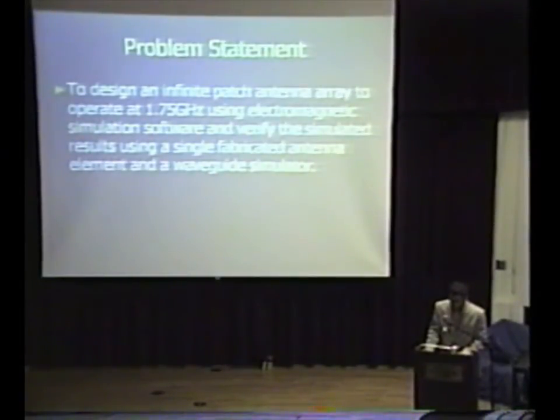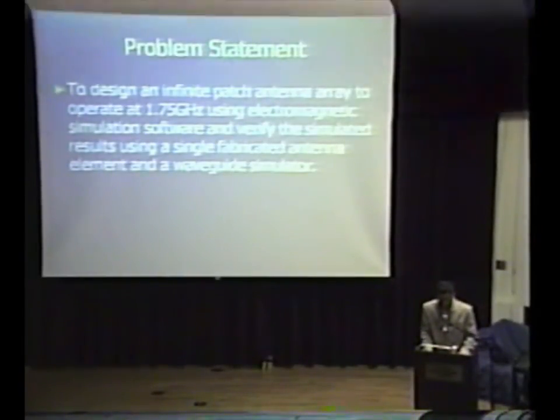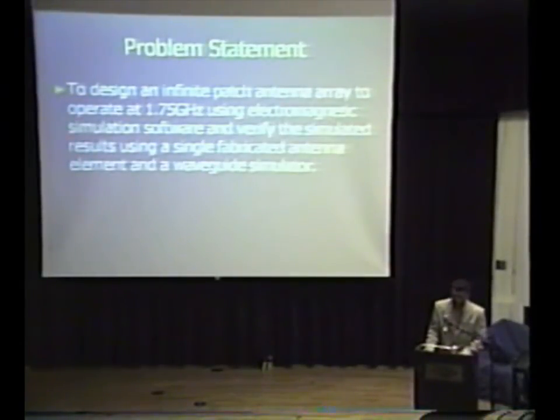An infinite array may seem like not a smart thing to design because it doesn't really exist, but it provides an accurate model of a single element surrounded by a large number of patches. It doesn't have to be infinite. And also the waveguide simulator allows you to use a single element rather than build the entire array and tune it that way, which reduces cost and time.